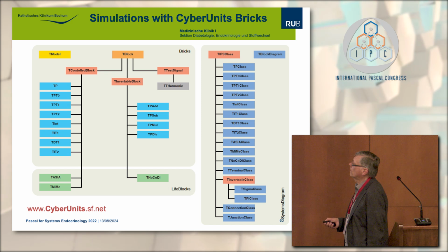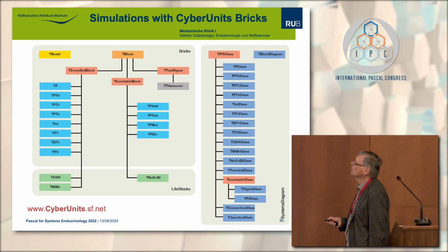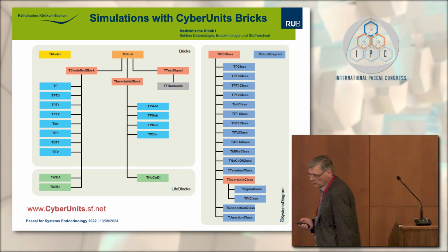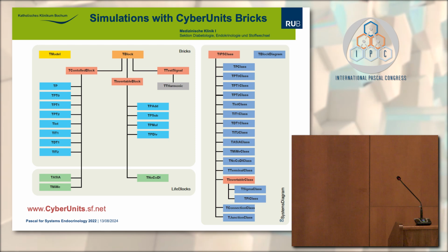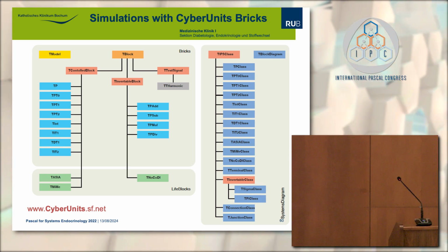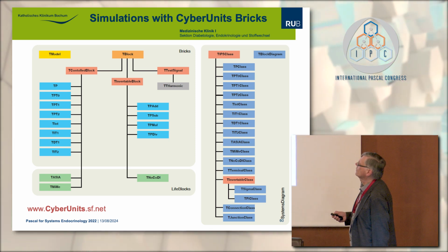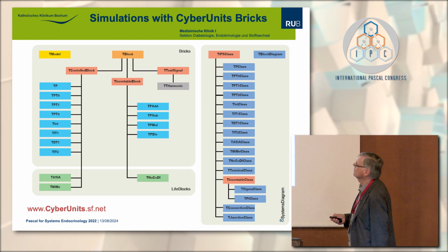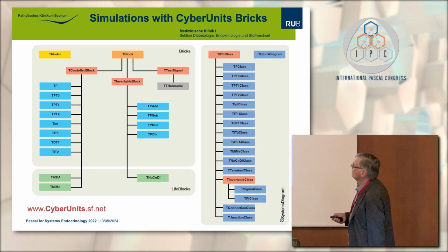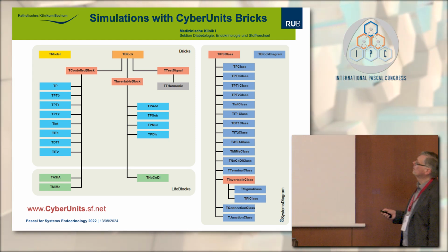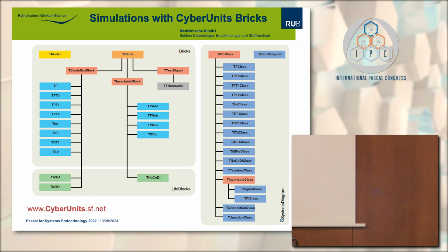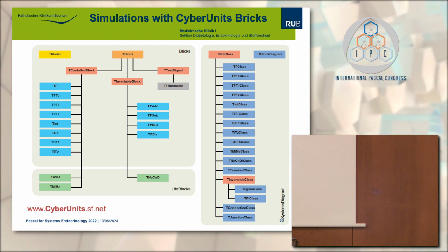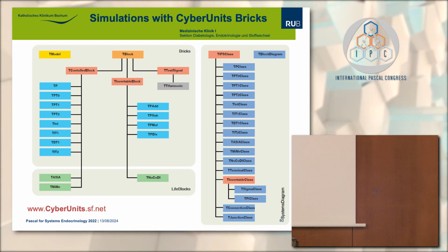And we have several building blocks, for example, a block for a proportional element here, a first order time element here, and a dead time element here. These are the simple blocks. Here are invertible blocks, which can have both positive and negative inputs, for example, an adder element or a multiplier.